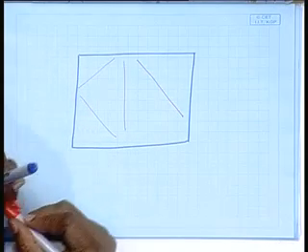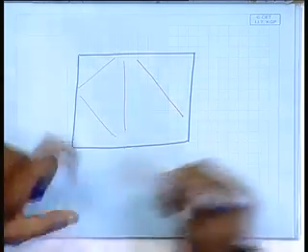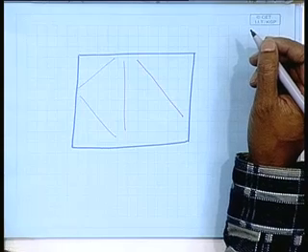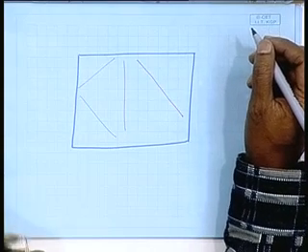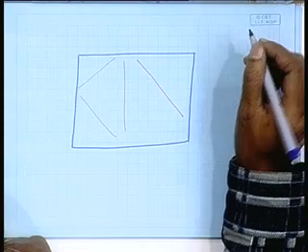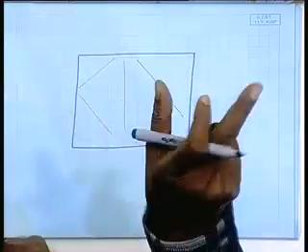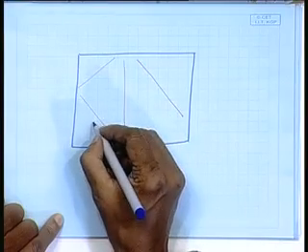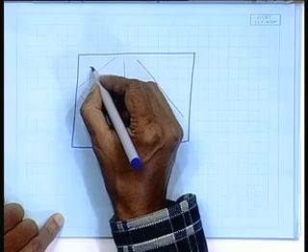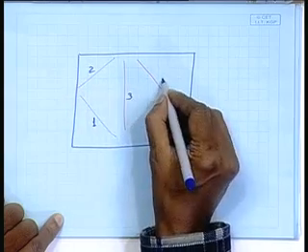So, the point is, if I can correlate what shape is needed, I mean correlate the pattern of heating lines to the desired shape, then I can generate that shape. Here I have just arbitrarily shown that this was my first heating line, this was my second, third, fourth.